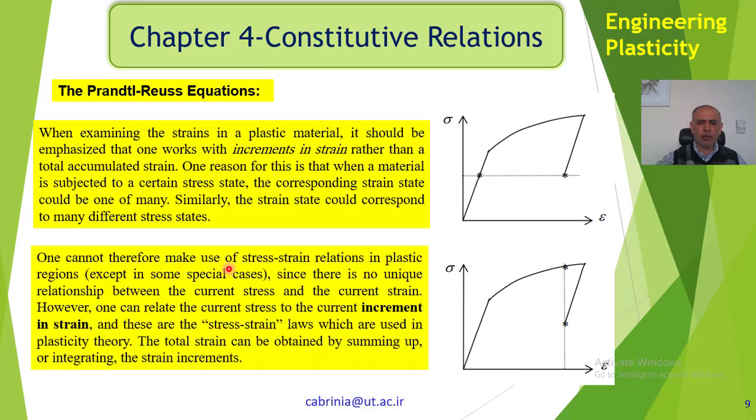One cannot therefore make use of stress-strain relations in the plastic region, since there is no unique relationship between the current stress and current strain. At this point, there is no straightforward relationship between the strain and stress. However, one can relate the current stress to the current incremental strain.